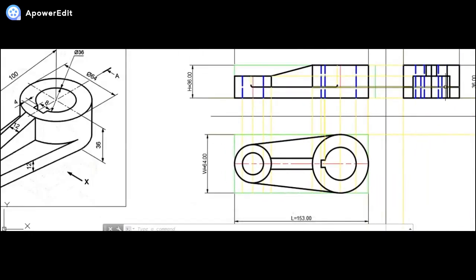So first of all, let us complete the hidden line part. So how do we get that? From here till here, the entire line, all the lines are going to be hidden from here till the surface till here. Everything is going to be hidden. So now once we are done with this, let us draw the tangents one by one.